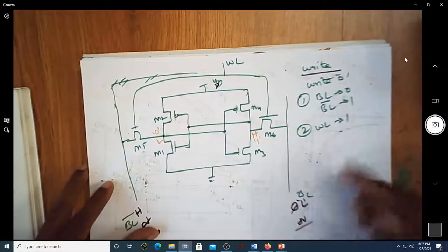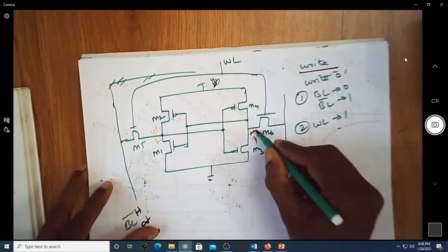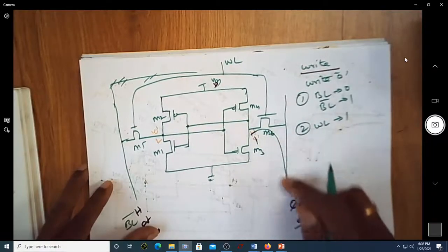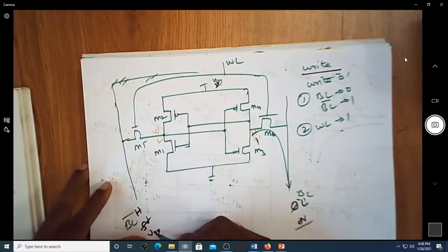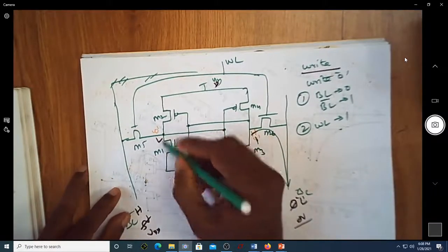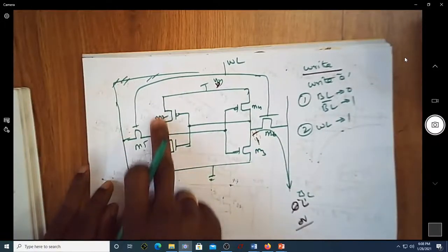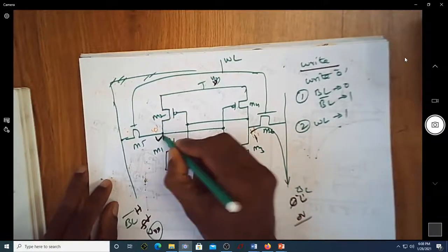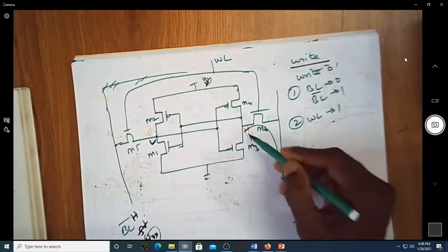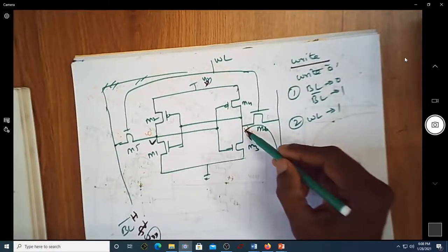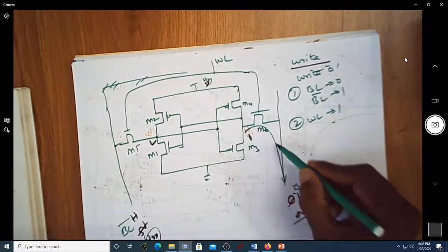Whenever you make this word line equal to 1, whatever 1 was there will get discharged through this, and whatever VDD was there, now we can see this is low. This VDD will not be allowed to rise because it was already low. This was actually low here. Now assume that I had a 1 here. This 1 will certainly be going to 0 through this M6 transistor.